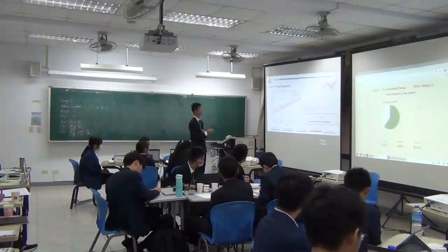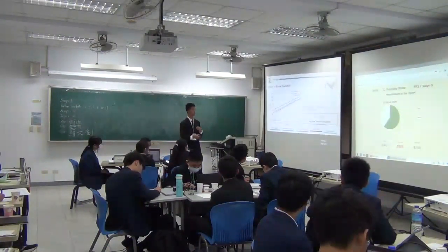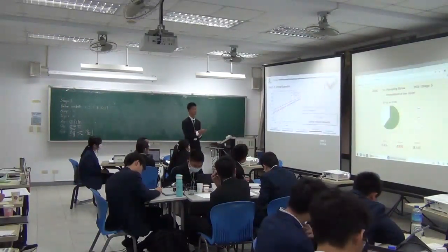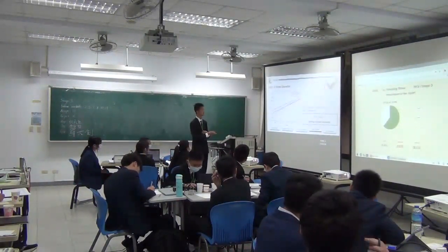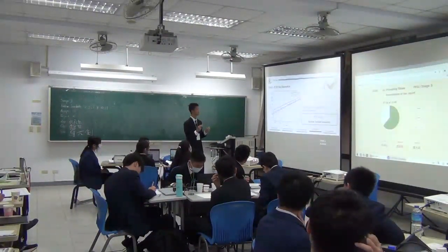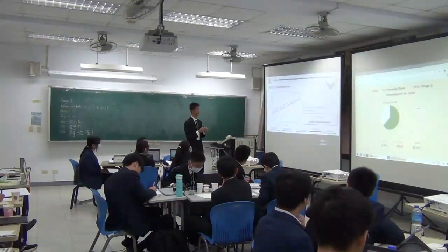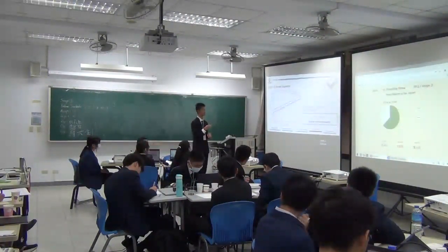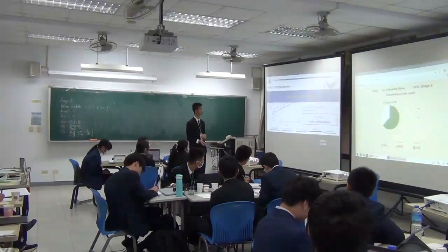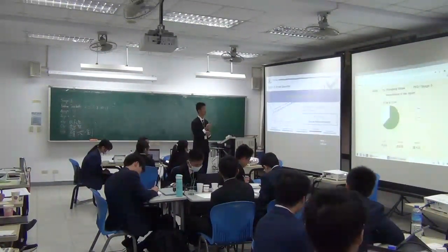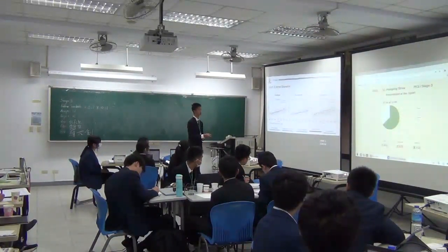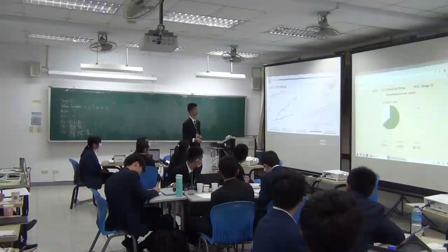So here's the effect of different straw diameter. The straw diameters are 4 millimeter, 8 millimeter, and 12 millimeter. So because there is surface tension that pulls the water upwards, if the straw diameter is smaller, then the surface tension is more significant, and the exit velocity will be higher. So a smaller diameter will have a higher V due to surface tension. And for the effect of different straw diameters, you can see that experiment and theory agree.